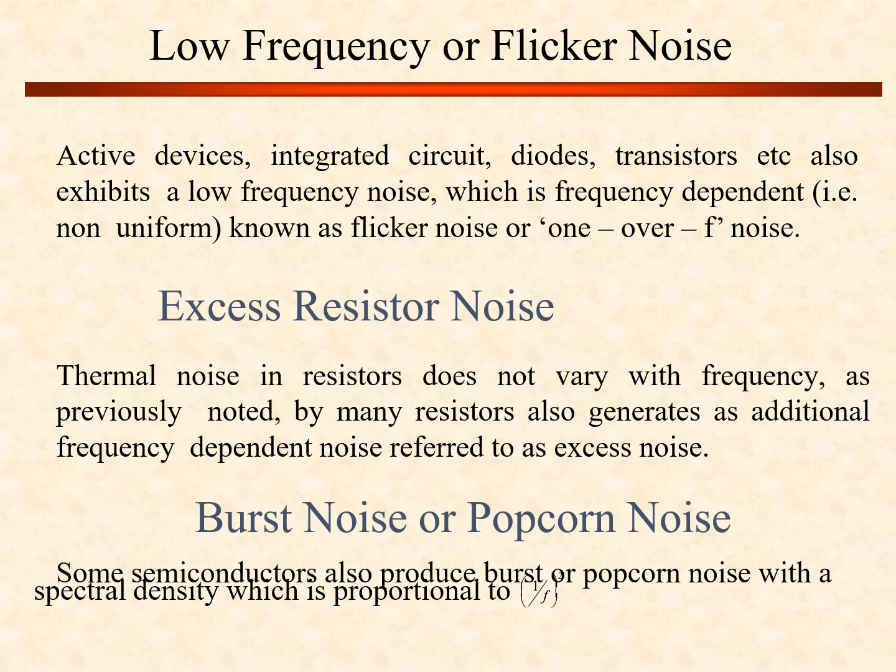Then excess resistor noise. Thermal noise in a resistor does not vary with frequency, but a resistor can also generate an additional frequency-dependent noise, which is referred to as excess noise. So the noise produced by the resistor at additional frequency is called excess noise.